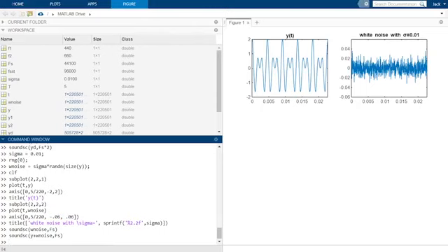Now let's try to create another type of noise to simulate a crackling effect that is a common type of noise we would hear on an old vinyl record. This is called salt and pepper noise. Salt and pepper noise includes very brief popping noises that can be simulated with intermittent spikes in the signal.